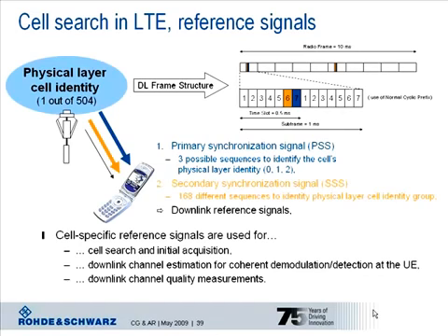The 2 synchronization signals are always transmitted in the first time slot of that subframe, where the primary synchronization signal occupies the last OFDM symbol, and the secondary synchronization signal the symbol before. The determination of the cell's identity enables the UE to examine the pseudo-random sequence used to generate the cell-specific downlink reference signals, as the initialization of the generator is based on the cell's identity and the used cyclic prefix, normal or extended. The information which type of cyclic prefix is used in that cell is derived here.